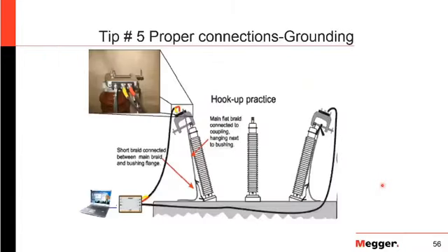And this will allow you to be repeatable each time, and make sure that if I do it, if you do it, if someone else does it, we're going to have the same connection and the same grounding point. So if you look here, you have this nice long piece, and it can go way past it, but then you have the short connection point to go to your quickest ground. So if it's a short bushing or a long bushing, you're still always grounding at the same point, and you're going to the first ground you can get connected to.